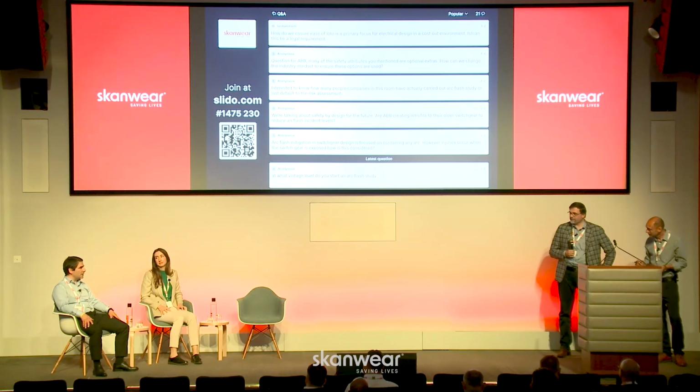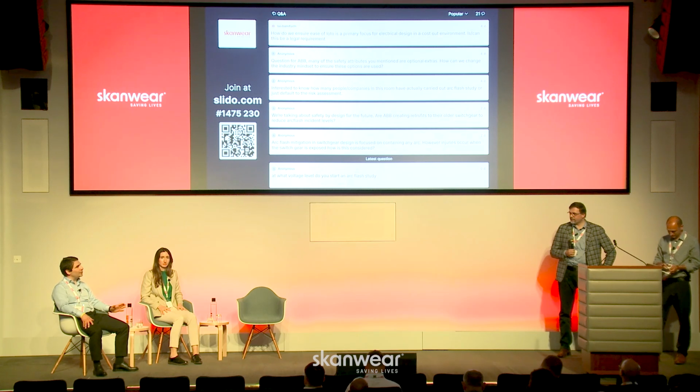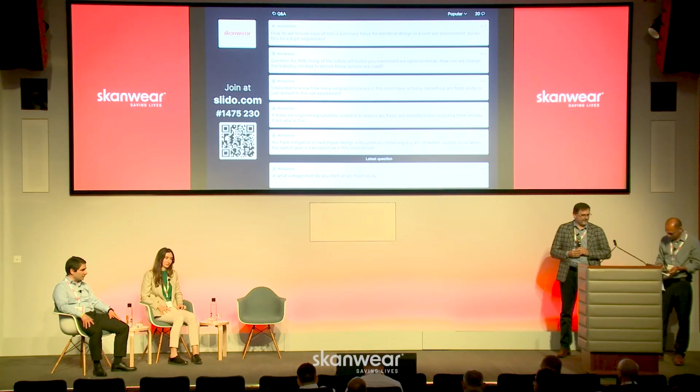It can be retrofitted. Well, we don't call it an arc quenching system in ABB medium voltage, we call it UFES. It's like an earth switch, which basically becomes conductive when there are high energy levels and a high voltage situation. So it's not the cheapest chip, I must admit, but it can be retrofitted, and comparing the potential of that device to save lives and to save the equipment itself, obviously it's not even comparable in terms of costing. Yeah, absolutely. But it is retrofittable, absolutely.